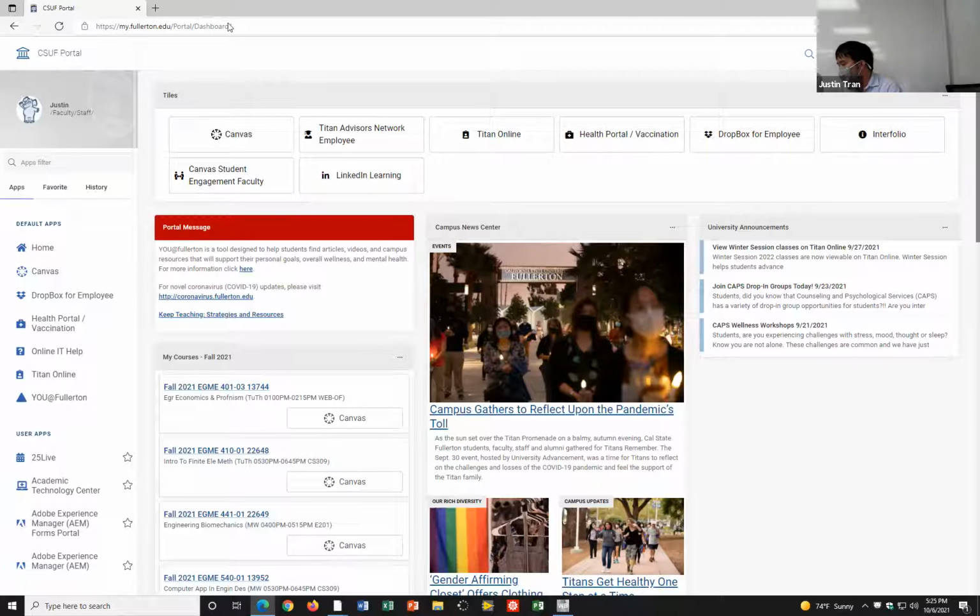So all you have to do is click and highlight faces. And you can click multiple by doing control click. And if you right click, there's an option there for hide faces. I think the hotkey for that is F8, but I usually just right click and click that. Okay. And so with that, you can gain access to the interfaces, and then you can apply pressure to those conditions. So the pressure will be pressure, actually. Yeah. Okay.